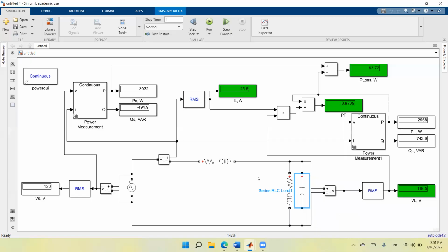At the beginning, we had a resistive inductive component for this load, and we compensated the inductive component by having a capacitive component. But the capacitive component now is more than the inductive component, then the entire load characteristic is resistive capacitive. So we have a capacitive component in the current. So this is why the current increases, the power factor starts decreasing, but it is a leading power factor now.